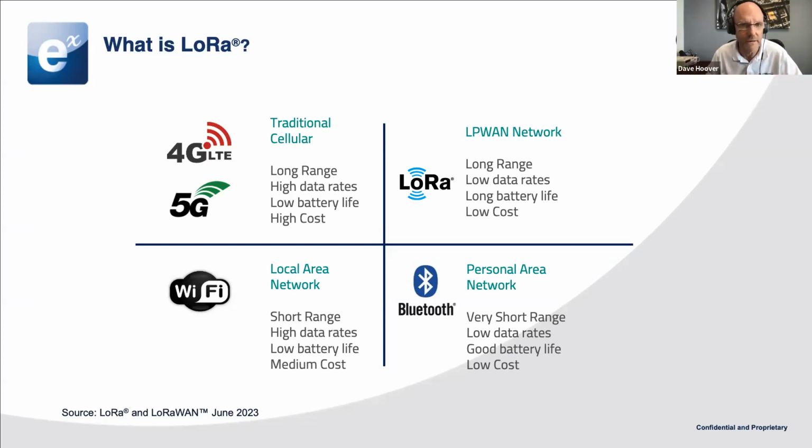And then obviously you have Wi-Fi. It's interesting, over the past few years it's been making a resurgence in terms of IoT applications. It used to be kind of a no-go for IoT applications due to IT considerations and getting onto clients' networks, especially in hospital applications. It's making a little bit of a resurgence, but again, a different beast. That's aiming for a medium distance and large amounts of bandwidth. And then Bluetooth goes toward the very battery efficient, but obviously very range constrained.